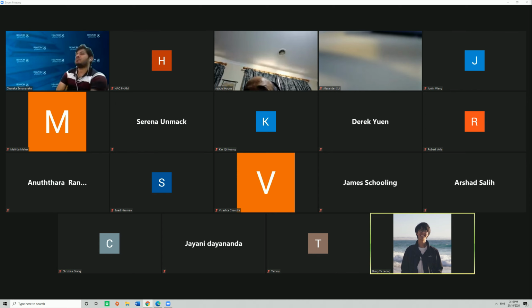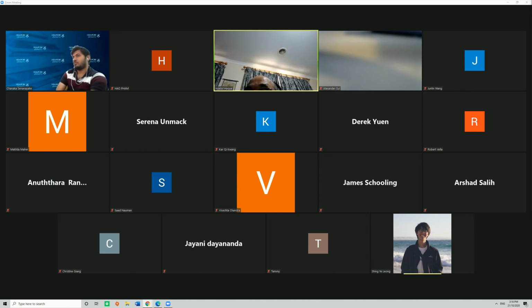Yeah, so for this practice set we don't need to find it, but for our task 2, you do. Try to check it, Shing. It's better to check whether that is meeting structural ULS or not. Otherwise, when you are executing your assignment 1, assignment 2, you start to go for a 1 meter diameter, but structurally it might fail, isn't it? So it is good, although I have given you 1 meter, I didn't say I checked it already. Nowhere am I saying that I checked it. So you can check whether that 1 meter is satisfying the structural ULS or not.